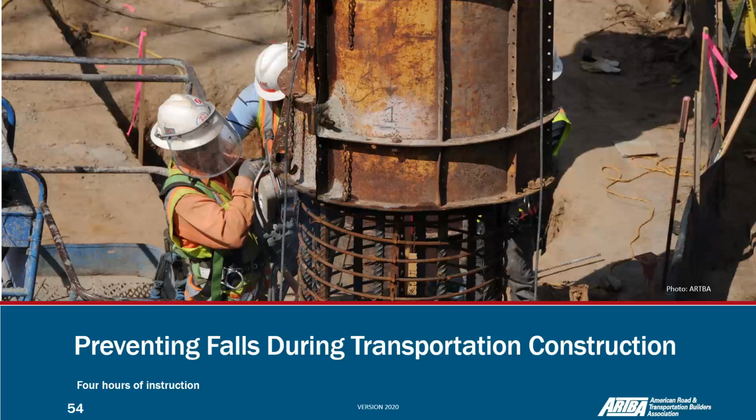We can also use a personal fall arrest system, and we are going to talk more about these requirements today, about all the personal protective equipment that they can use. We were also talking about scaffolds. When our workers are working on scaffolds, they need fall protection whenever they are 10 feet high or more, and also the 15 feet rule.